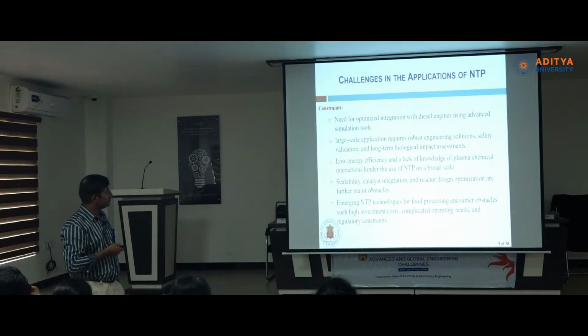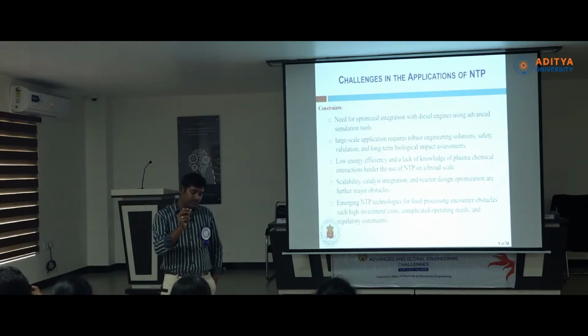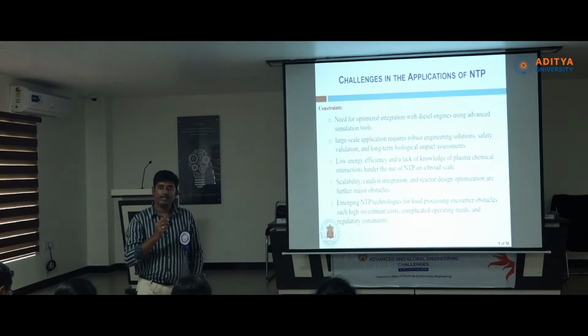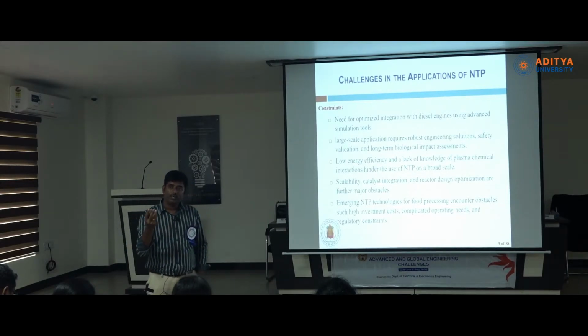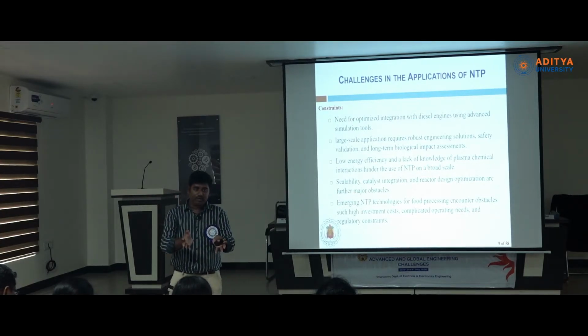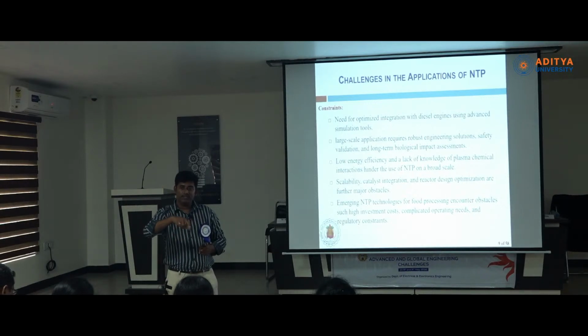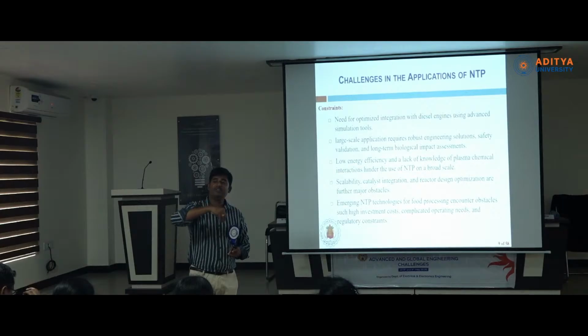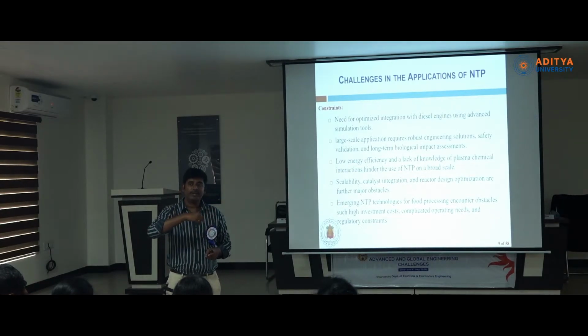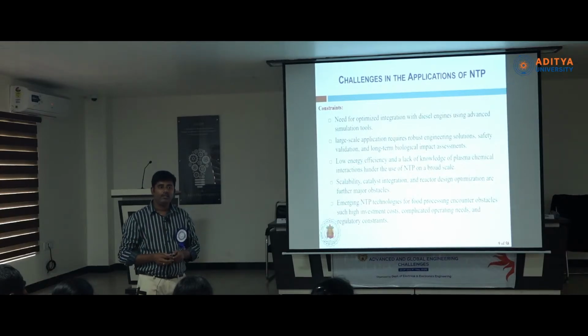Then large scale application is another constraint. Small scale you can do, like the basic methodology I have shown you in this non-thermal plasma, where the reactor is of 1.5 centimeter diameter. How much time does it take to treat a bowl of water using this reactor? Let us say we are applying this technique for water treatment. We need to place a bowl of water under this plasma and expose this water to the plasma jet. Then frequently we need to mix it, because the treatment is happening at surface level basically. Then the water gets treated in, let us say, 5 minutes, a bowl of water. Then if you need to do it on a large scale, you can imagine how much time it takes.